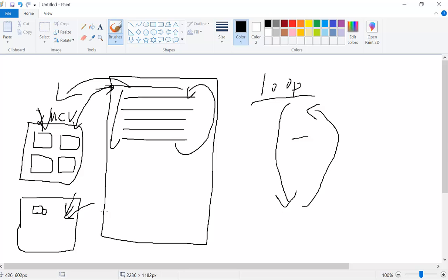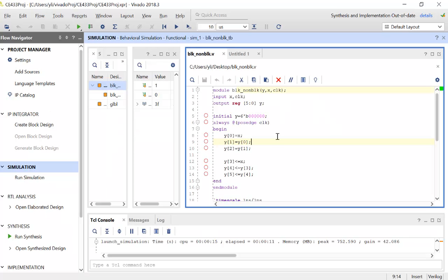It's like a photo. You take a photo, and that's the entire digital block. It's not being executed line by line and sequentially. So that's why when you are programming an FPGA using Verilog, you have to have that concept in mind. It's different. It's not being executed from the top to the bottom. It's like a picture. It's just being programmed and wired up at once.